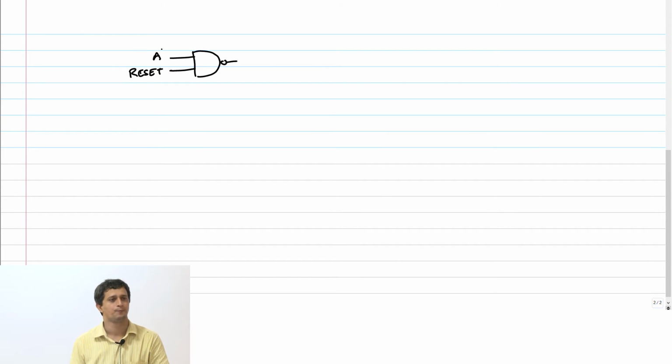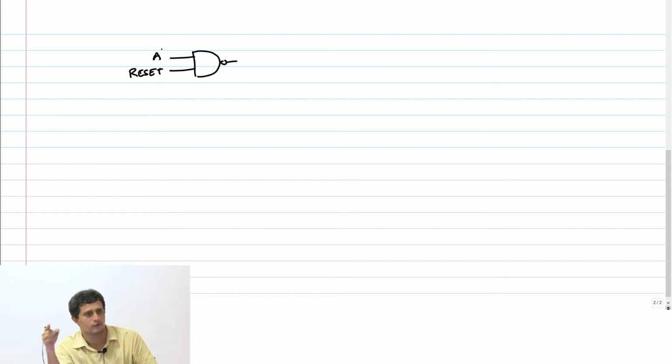So what is an example here? Suppose I have a NAND gate, let's say with a signal like this, reset and an input A. Now this reset is very not timing critical, right? So therefore you connect that guy to the bottom transistor. The signal A is basically the critical signal which is going to control the stuff inside your circuit, right? So that has to switch as fast as possible.